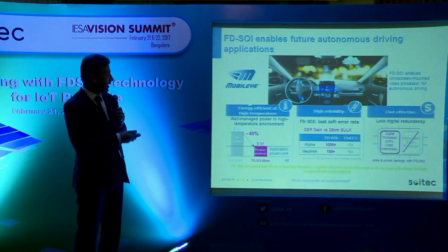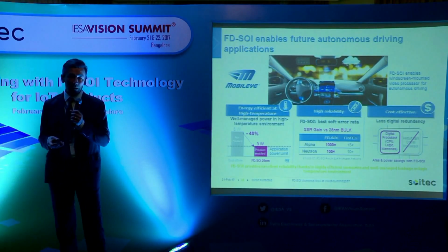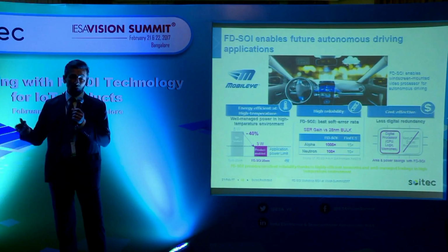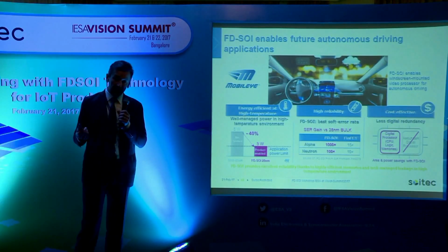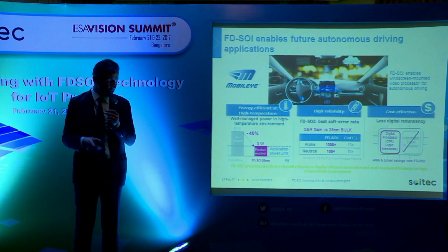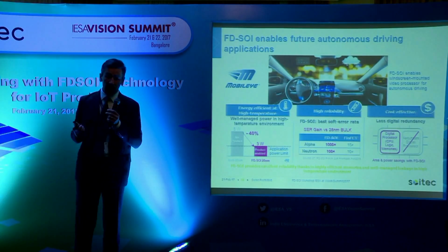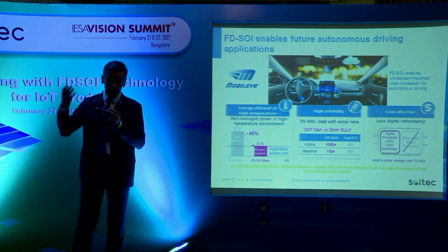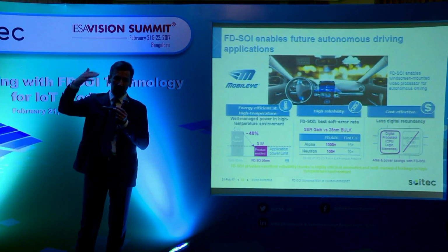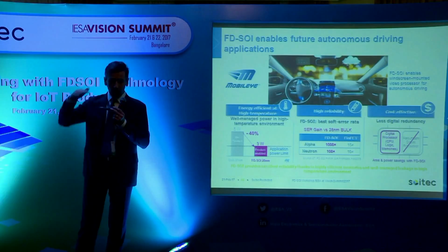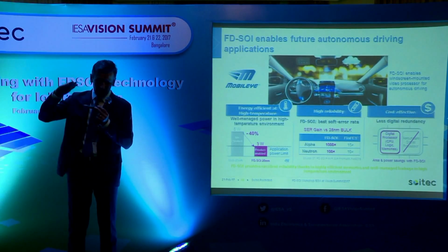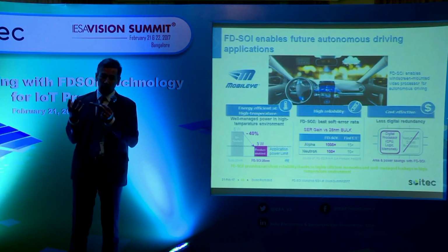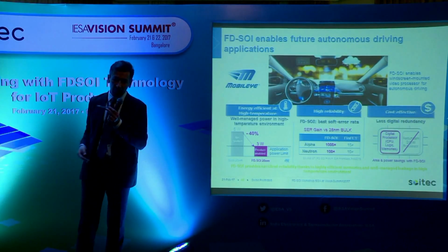Here the example is Mobileye, and maybe many of you know Mobileye, this Israeli company, one of the leaders for ADAS applications and computing. There's actually a couple of things worth mentioning here. Some applications require computing, for example, a car camera built into the windshield, on the glass. This can work only if the power consumption of this processor is very low. Otherwise, there is too much heat on the glass, and the chip will not function.